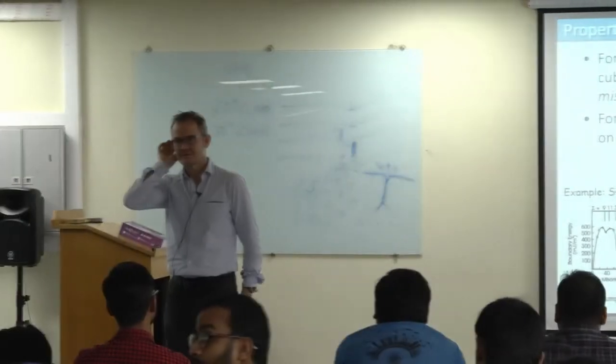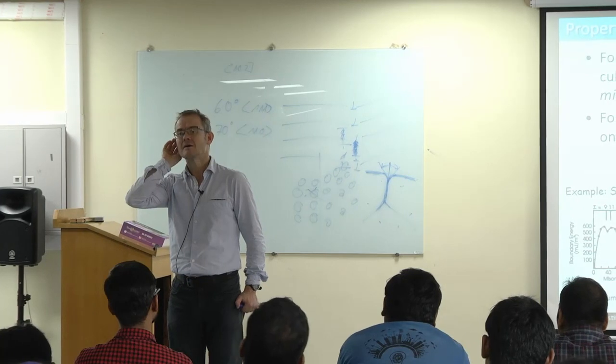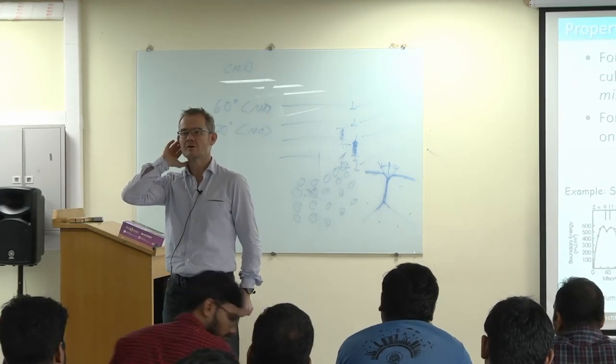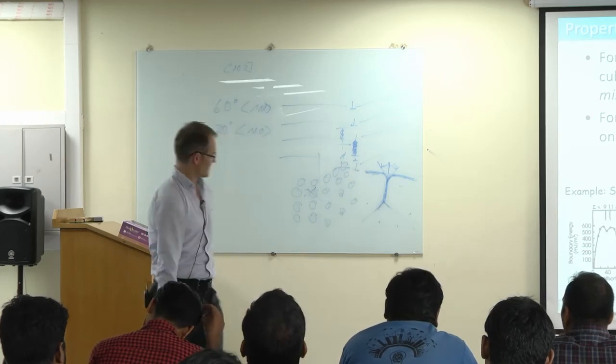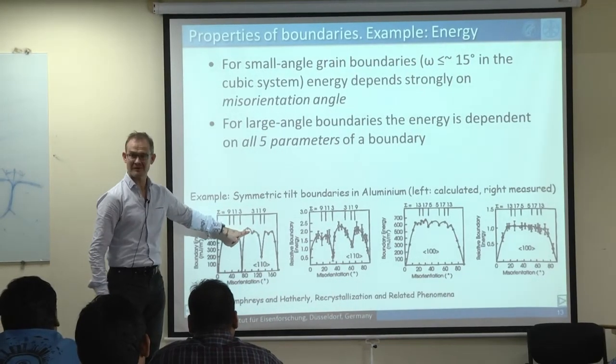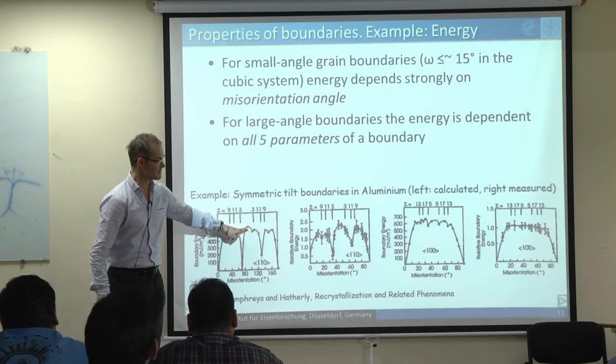So are they better than the random high angle boundaries, or in terms of energy, are they lower still? What is lower? Coherent sigma. Incoherent. Some are, obviously. Now, as you see, there is a little dip. This is an incoherent sigma 3 boundary. It's a little bit lower, no?